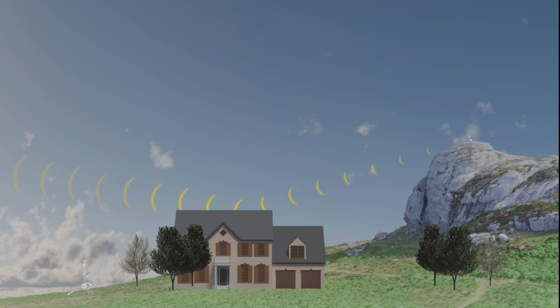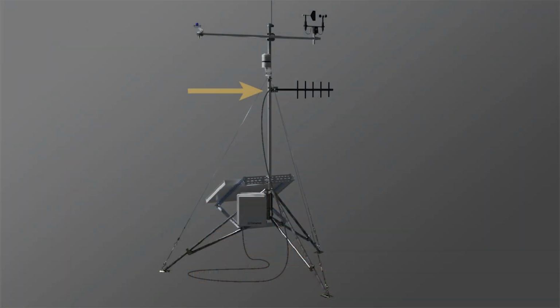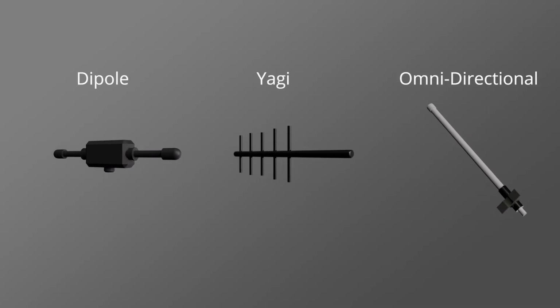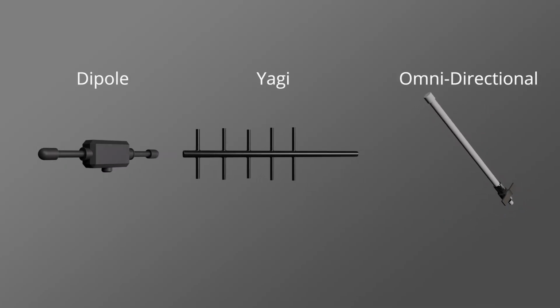If possible, avoid installing radios and antennas near large, flat, reflective surfaces that could increase multipath reflections. Mount the antenna as high as possible without interfering with any sensors, and use the shortest cable possible to connect the antenna to the radio. Once locations are selected, choose transmitter and receiver antennas that will provide dependable communication for the specific link.